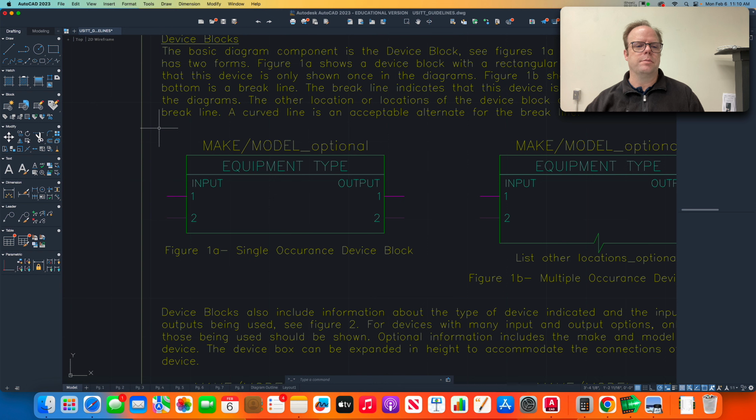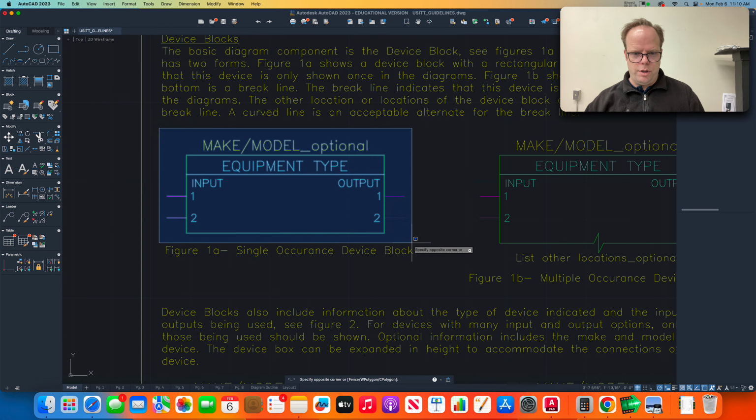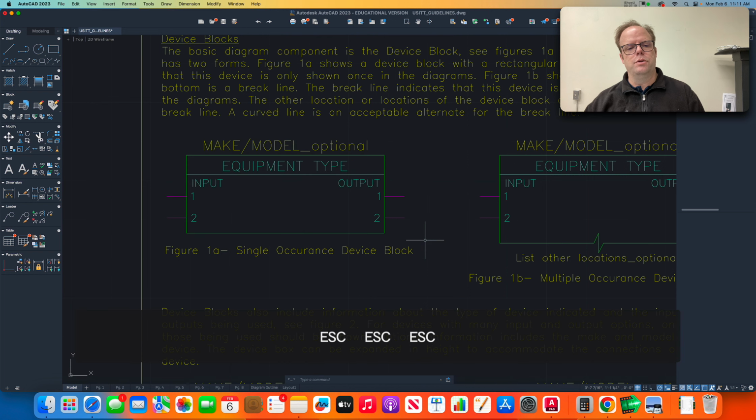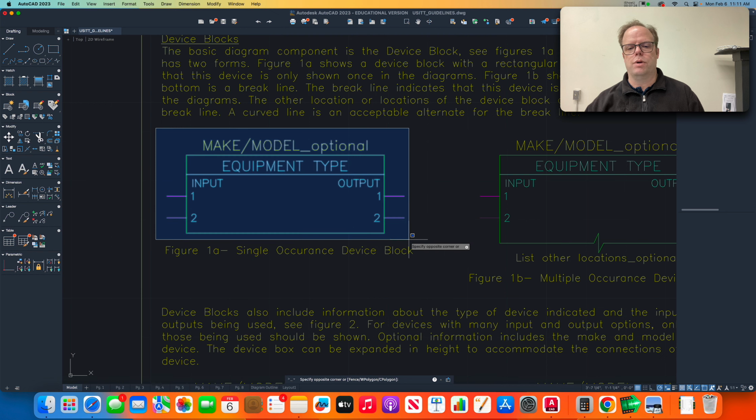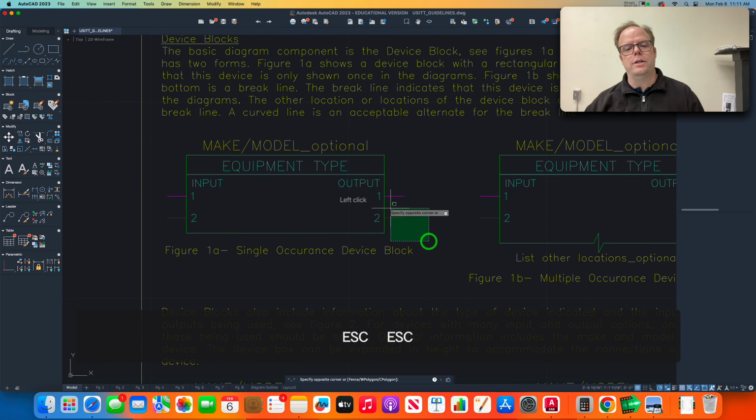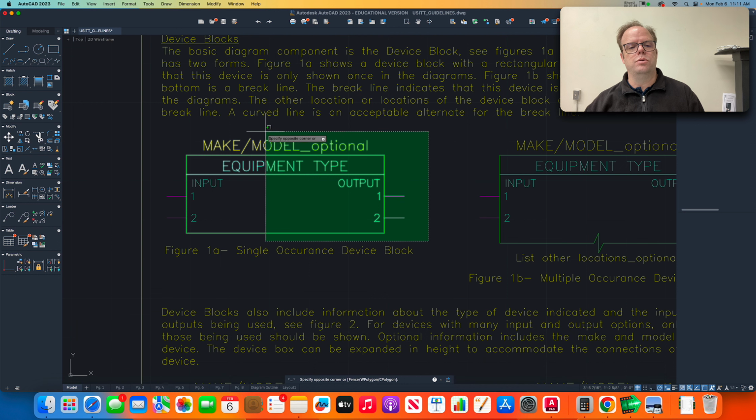Now what I'm gonna do is use my mouse and drag over it, okay? Now remember the rules about selecting. If you start from the left and drag to the right, it will select everything that is completely captured inside of that rectangle you drew. If you start from the right and drag left, it's going to grab everything that is only partially enclosed in the rectangle you drew.